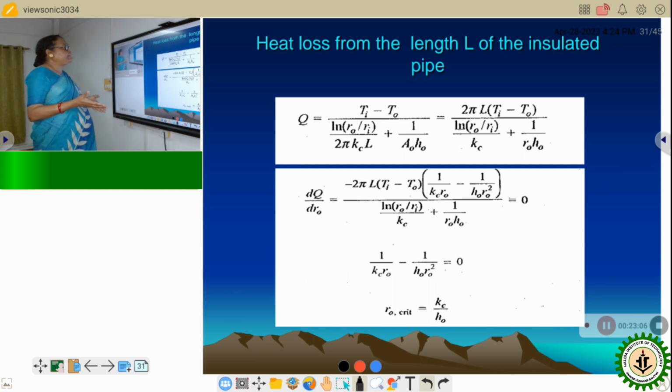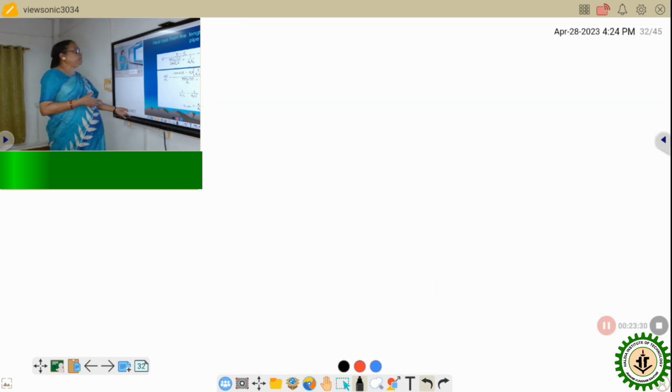That is for the insulated pipe. So if I want to know the critical radius, you have to set this expression to 0, and from that equation we get that Rc, the critical radius, is Kc by Ho. Kc is the thermal conductivity, Ho is the outside film heat transfer coefficient.